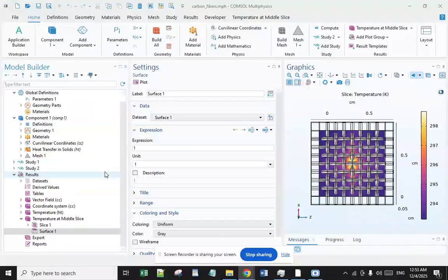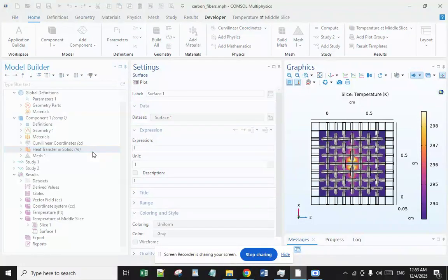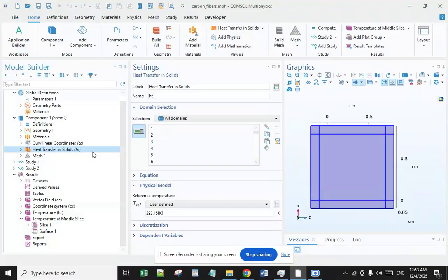The equation here in this heat transfer in solids module was linearly fitted to obtain the thermal diffusivity from the gradient of the line, where a constant rate of heat loss to the ambient environment was assumed, represented by the intercept of the linear fit. Using the C_p value obtained from the DSC experiment, the transverse and longitudinal thermal conductivities were determined from the transverse and longitudinal thermal diffusivities respectively.